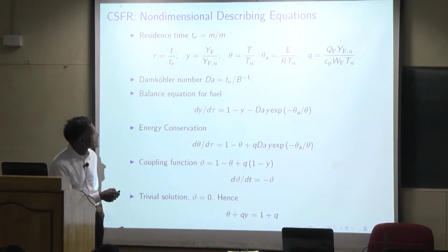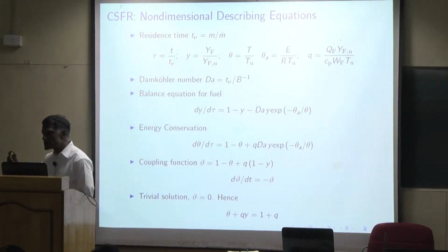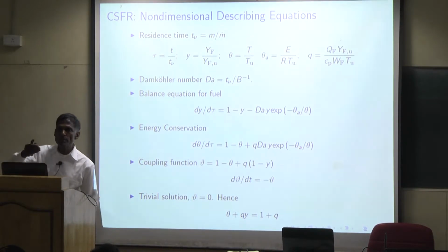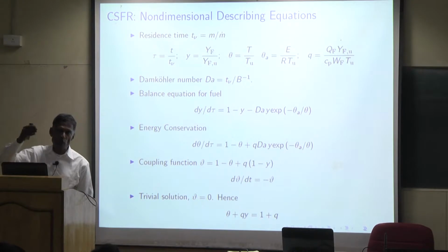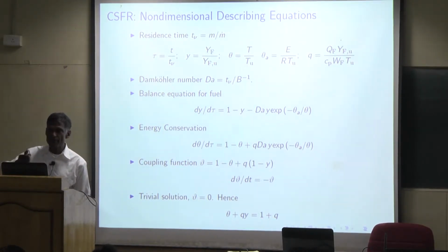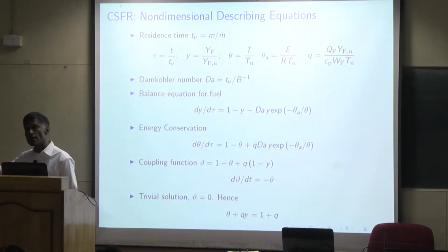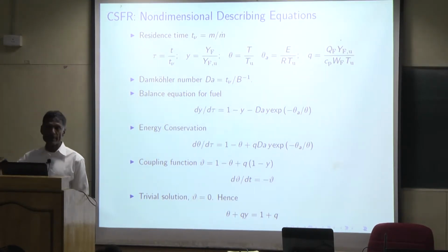No, I think the Damkohler number is usually based on, even if you put the concentration, we usually put only the initial concentration of the fuel. We do not put the instantaneous one. The point is, in asymptotic analysis, the parameters that appear should be standalone. They should only depend on the initial concentration of the fuel or the initial concentration of the reactants. You're not allowed to change that. So for the Damkohler number, that residence time you have taken, will that correspond to the flow velocity, or the turnover time?